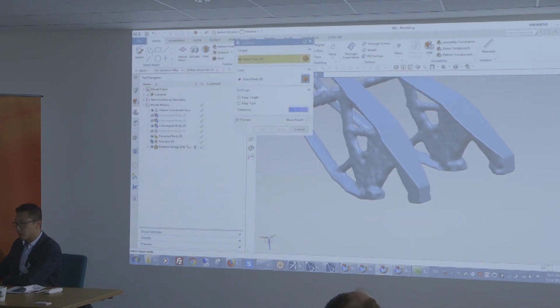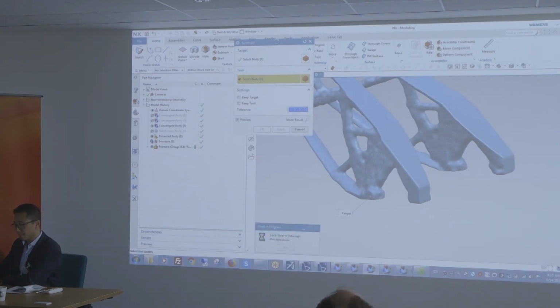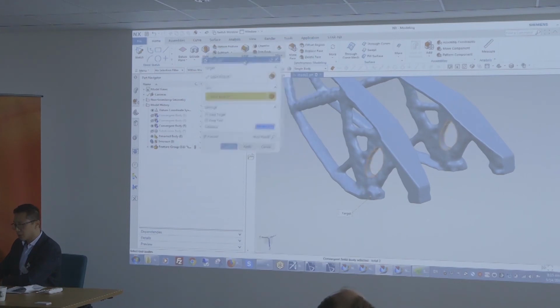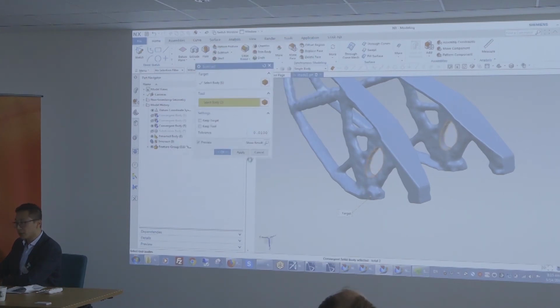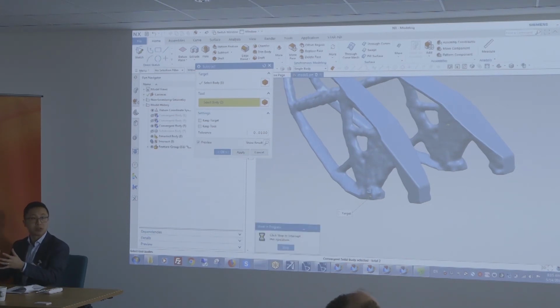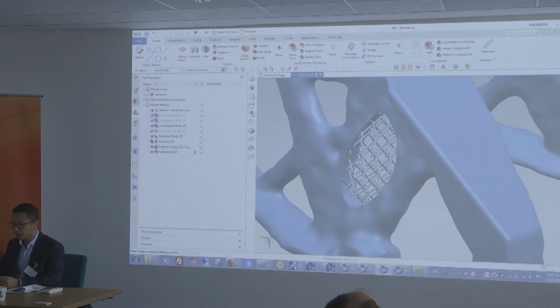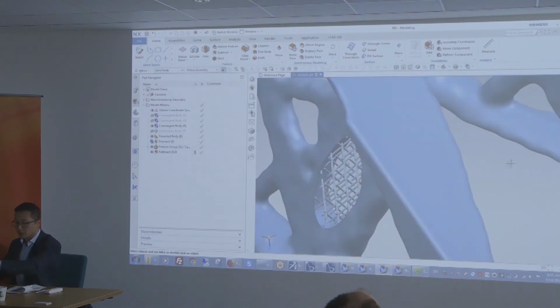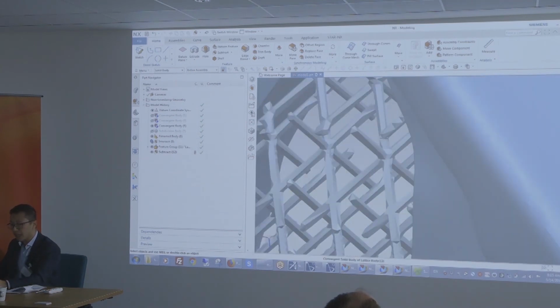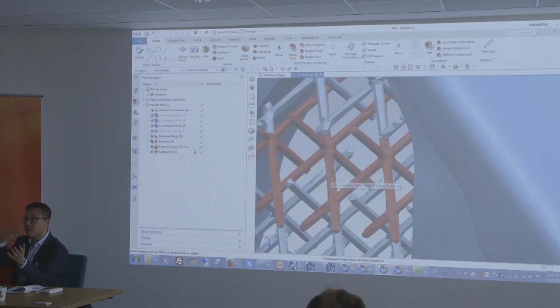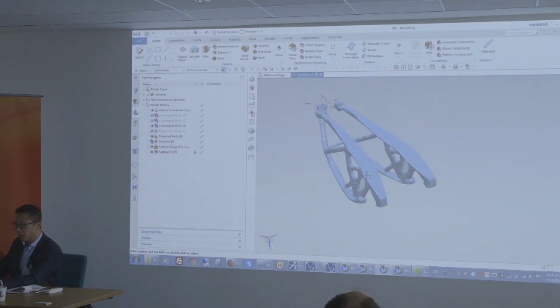And then the last part is to subtract, which is to remove the original material, and you'll see that what I'm left with is a nice and smooth lattice meshing on top of a convergent modeling body. See the lattices? From a visual standpoint, you still see kind of the edges, but as soon as we go into an additive manufacturing environment or a structural environment, you'll see that these get converted into the right format. And you'll see what I mean in just a second.